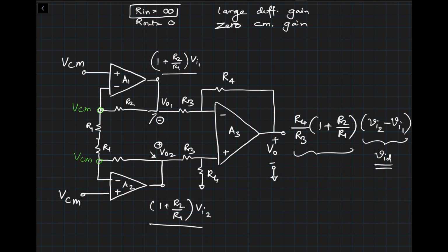Now comes the interesting point. Earlier, we had a ground connection over here, and what that did is it caused a common mode current of VCM divided by R1 to flow through this circuit like this. VCM divided by R1, and that current totally flew through this ground connection that we had. Okay, so then you would have 2 VCM divided by R1, and everything else is the same as what we discussed. So that common mode gets amplified at VO1 and VO2. As soon as I remove this connection, something changes.